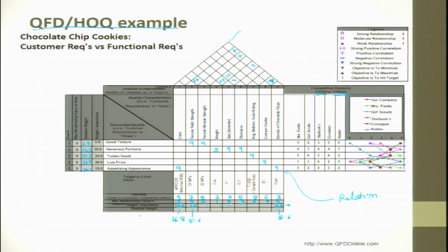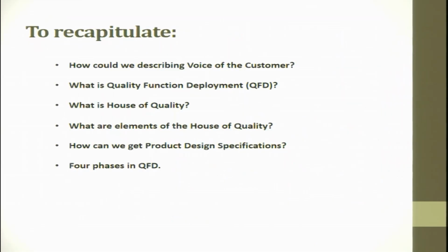So this is the relative weightages, and then from here I try to pick the values and start working on it. So this is how you fill out the house of quality in quality function deployment. If you start filling up all the relationships, you can get a complete value. You get all the numbers, and from these numbers you can start giving the relative weightages. From these relative weightages, you know the significant parameters, and you start attacking the significant parameters to meet the customer demand. And here it talks about how the company's performance is with respect to your product. So, with this we would like to come to an end for this quality function deployment.